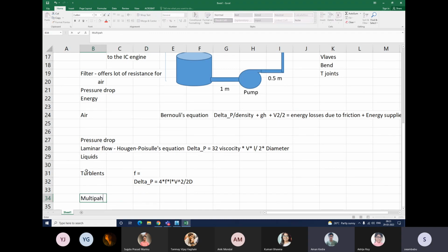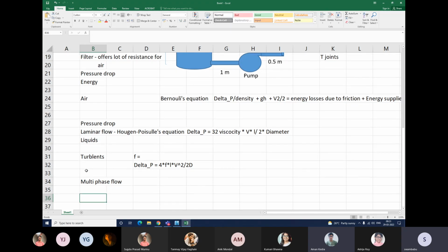For multiphase flow, we have correlations for the friction factor, and so it is a little complicated, like we have partially vapor, partially liquid. But all three cases we can solve using DWSIM. Different methods are available in DWSIM or any other process simulator to estimate the pressure drop.